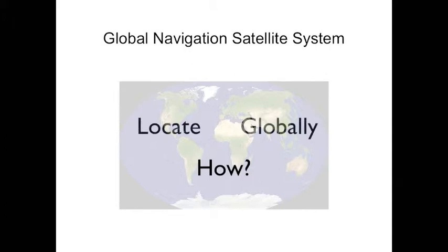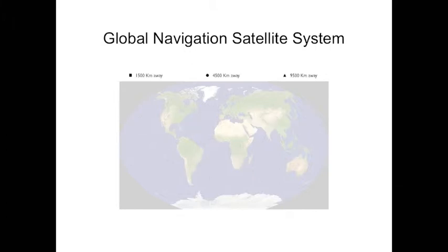The idea behind GNSS location is quite simple. If you know the distance between you and some given references, and you also happen to know the exact location of these references, you can calculate your own position by applying trilateration computation. That works just fine, but how do you calculate these distances?